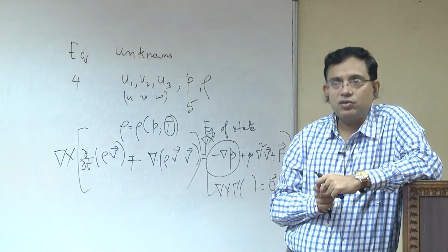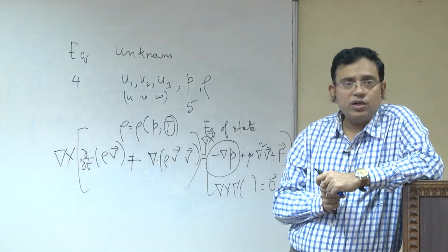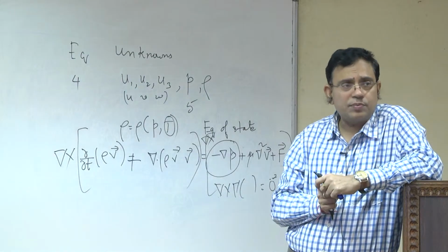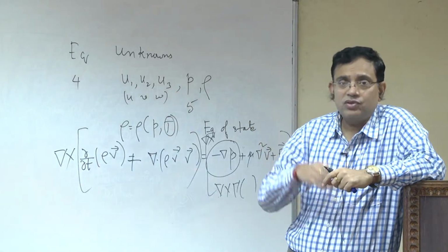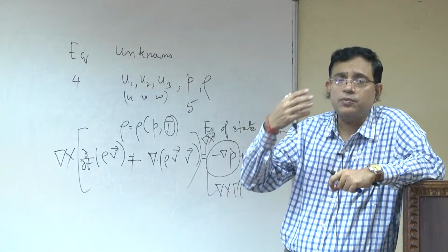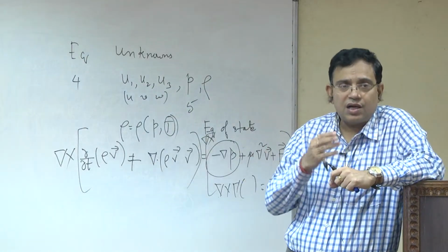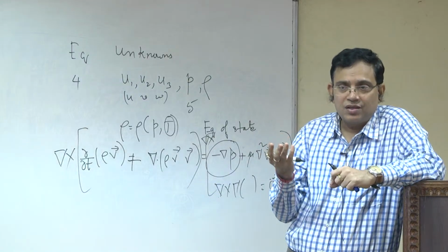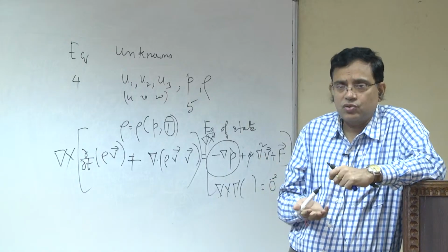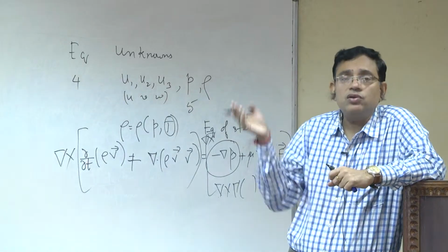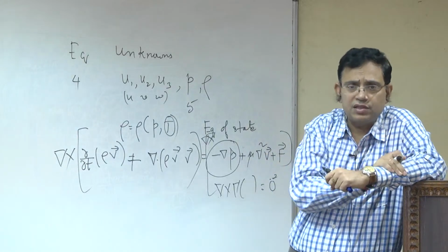To give a boundary condition in a physical problem, it is quite intuitive that if you have the physical description of the problem in terms of velocity and pressure, you can write something which is the physical problem. So, these are called primary variables or primitive variables. The stream function and vorticity are mathematical variables. They are derived variables and not primitive variables. So, making boundary conditions for them itself can be a problem for a physical system.